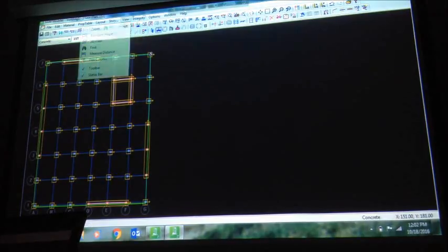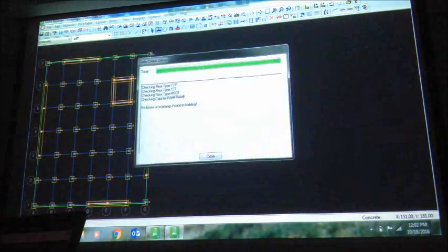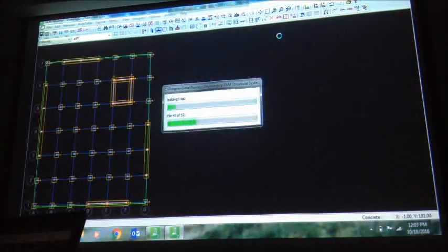One thing I strongly suggest is to check whether you have any problem with the model. So go to integrity, data check, go for an integrated check, that means gravity and frames, everything. Click OK. No errors, no warnings, so far it's okay. If there is an error, you cannot actually move or proceed, so you have to fix that error. Okay? That's where I will come into play in your model. Okay, let's save it. So far in 1 hour we are done with our modeling.